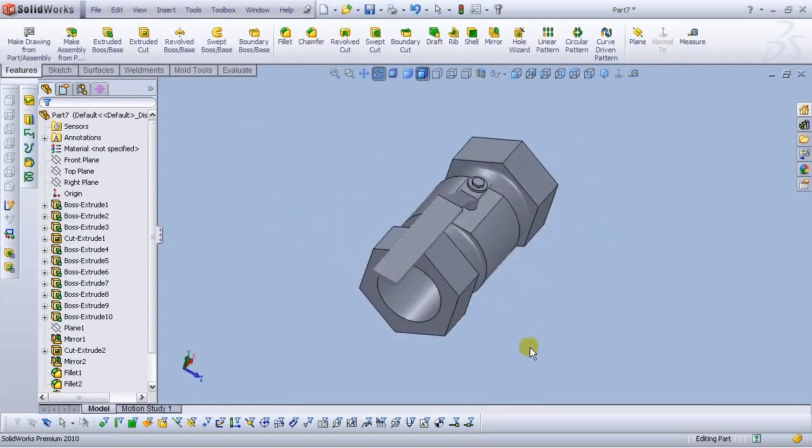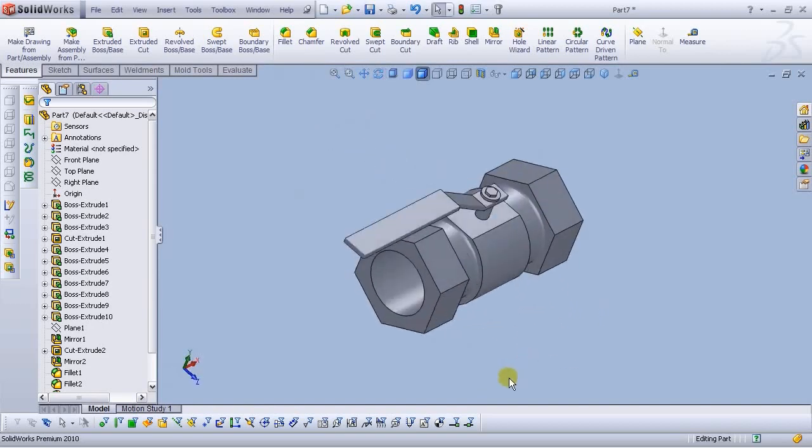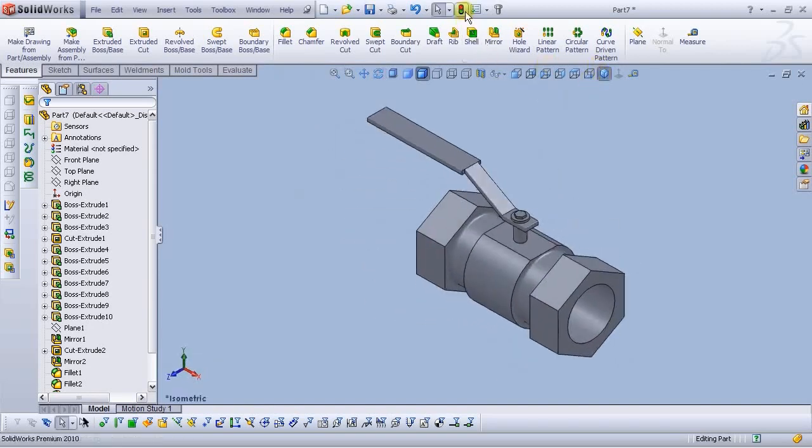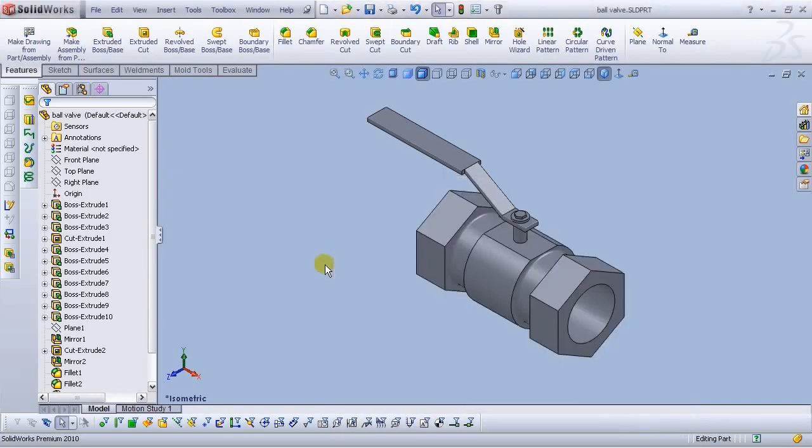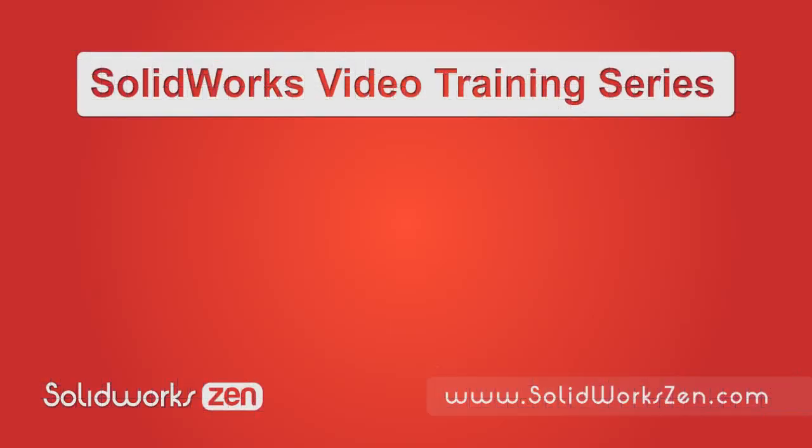Now let's do this on another side. We can use another mirror, plane to mirror, and features to mirror like this. OK. Now let's add some fillets. 0.3 millimeters fillets. Make it on this tab. It's too much.